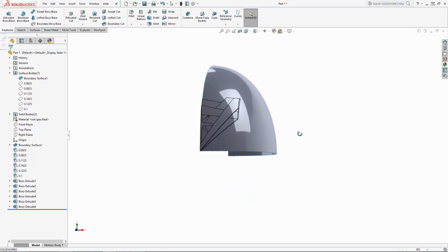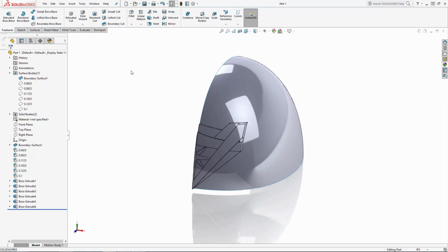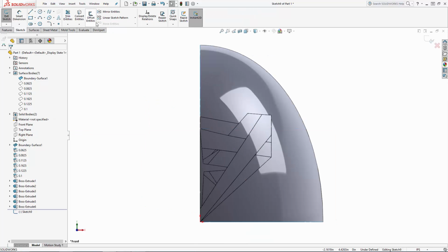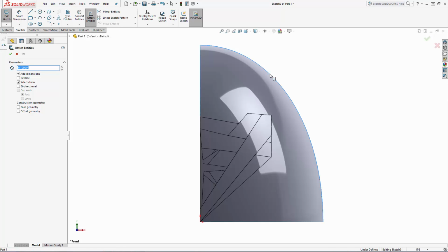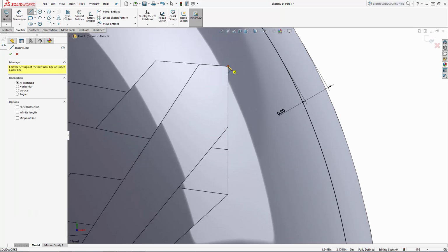Now at the center portion of the design, at a stopping point, I'm going to begin modeling a portion of the band that wraps around the head. Again, we'll sketch on the front plane, and I'm going to just offset from the outer edge of our quote-unquote head reference surface 0.2 inches, and use the Line tool to connect the band to the center design.